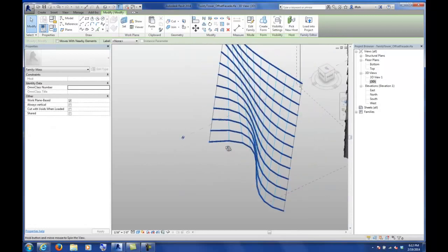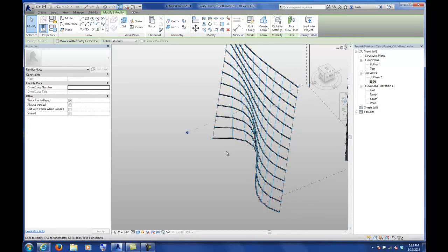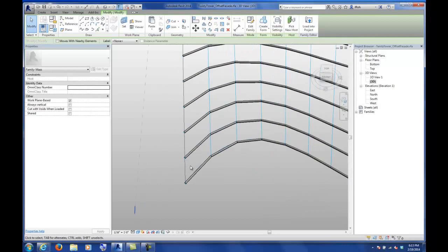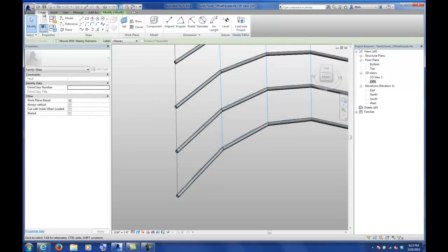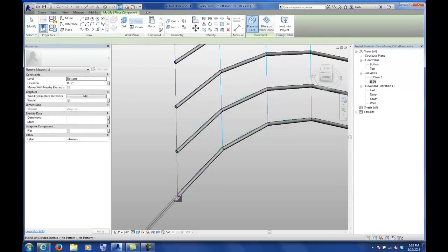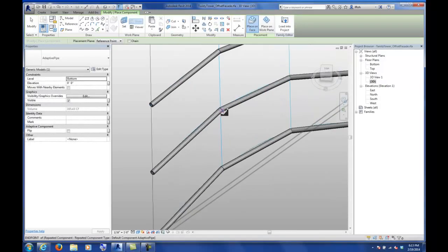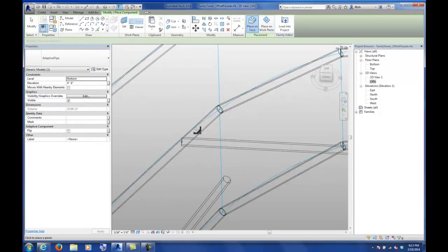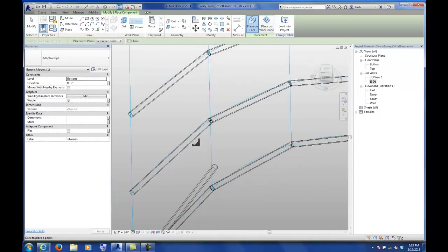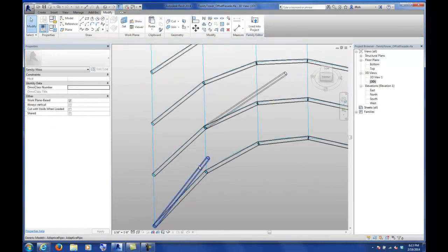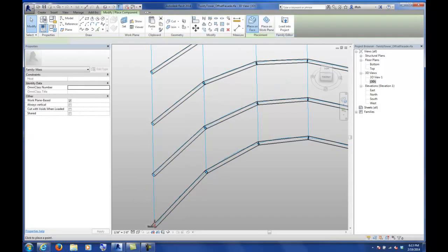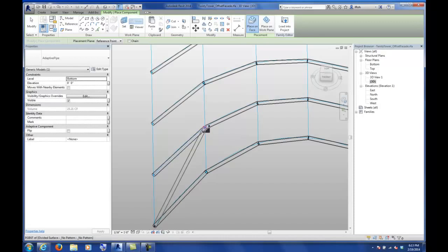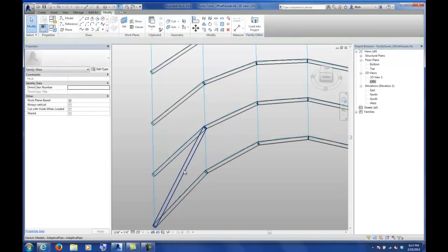So you can start to imagine, depending on how I snap to things, I should be able to do another one here. Let me hit create component and go kind of diagonal. You have to make sure that you're snapping to the points. You sometimes have to, when you have solid geometry, go into a wireframe view. Nope, that didn't work. Create component. Go back. And again, I should be able to repeat this one.